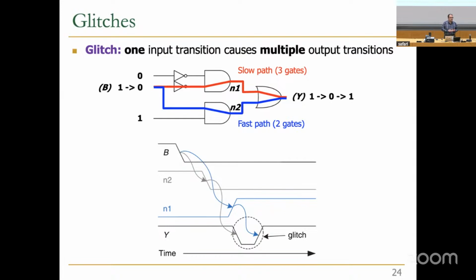No, it's not probability. First of all, these delays, contamination delay and propagation delay, have very exact meanings. For example, propagation delay means 50% of input to 50% of output, something like that. So if you consider that, then you cannot easily say propagation delay minus that. So these are not that accurate. But I like your abstraction, it's good for understanding.